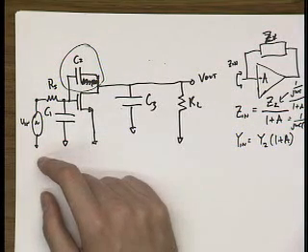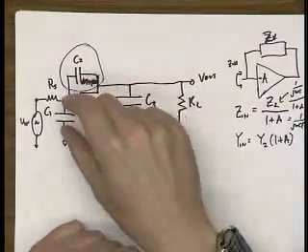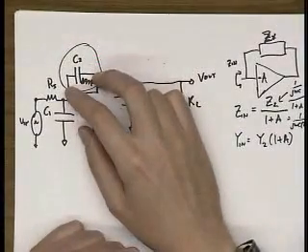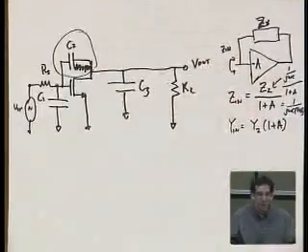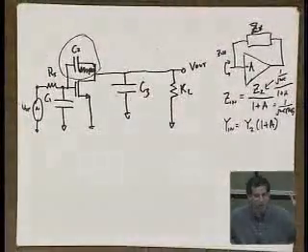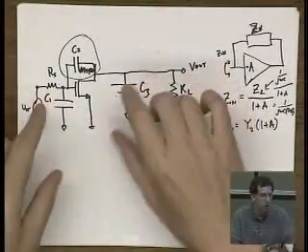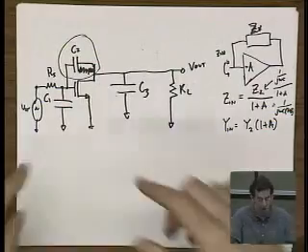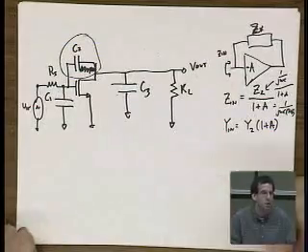Now, how can you figure out how many poles there are? There are a couple of different ways, and there's a way that I learned by looking at some other material that really is intuitive and easy. It's figuring out how many of these capacitors, in a DC sense, can have an independent voltage set across them, okay? And what do I mean by that? Let's assume that at a snapshot in time, these capacitors could have any voltage on them independent of what the overall voltages on the other terminals are, because these capacitors are storage devices. The more storage devices you have, the more poles you have.